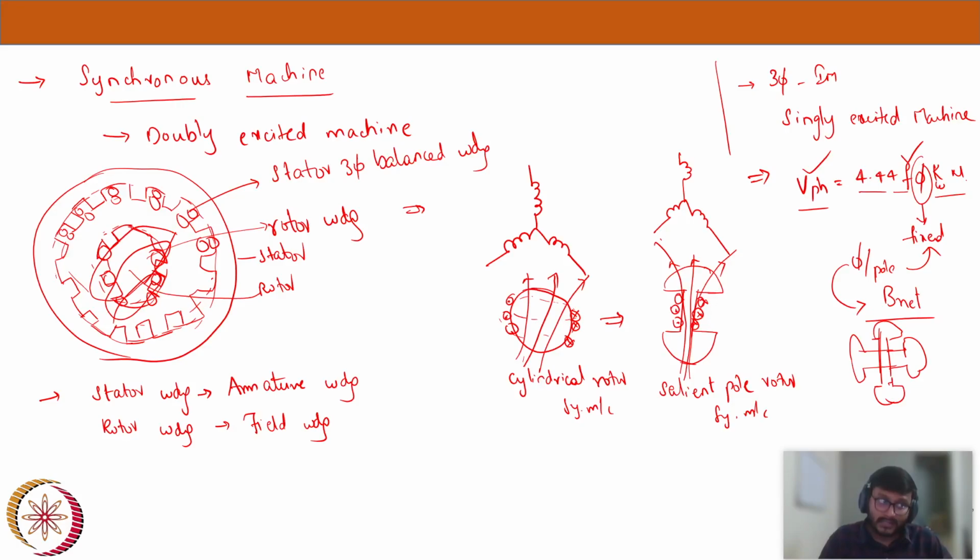So this particular characteristic of drawing the magnetizing current from the supply makes the motor have a very low power factor. It's not that very low, but it does have a low power factor when compared to other machines. Particularly during light load condition, as I said, this magnetizing current will make the power factor almost 90 degrees lag, that is zero power factor.